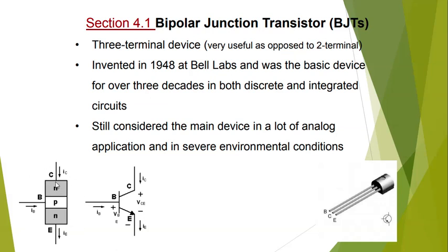It's because if you remember, a diode was a PN junction. It means one p-type semiconductor and one n-type semiconductor were put together and created the diode. A transistor is made of 3 different pieces of semiconductors: one n-type, one p-type in the middle, and another n-type. This is called an NPN transistor. We have a different type of transistor, we call it PNP. In that one, there is a p-type here first, then an n-type, then a p-type.